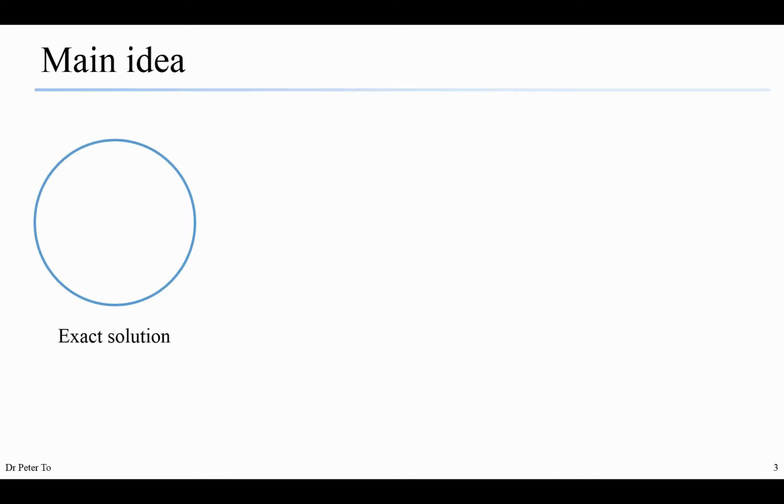Secondly, after the symmetry reduction, you need to choose the model type. It can be 1D, 2D, 3D shell, or 3D solid. After selecting the model type, you have to think about the resolution of the geometry. That means some detail may be omitted and it will not influence your solutions.